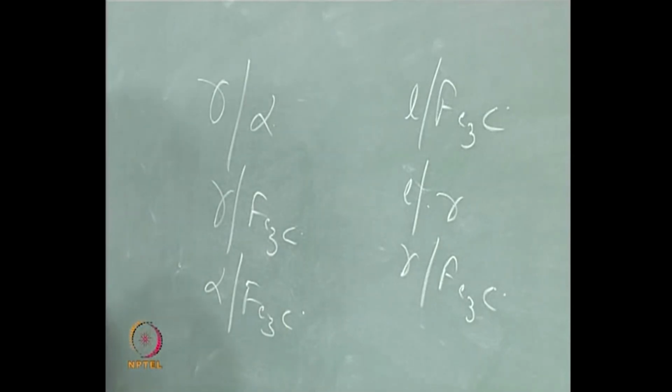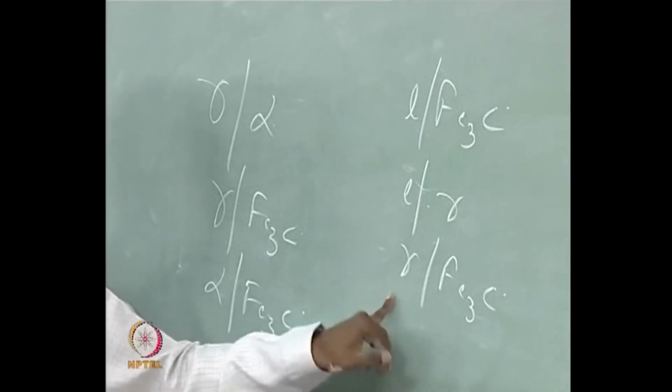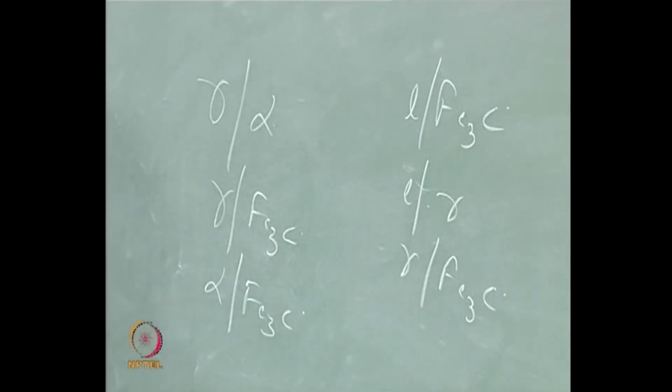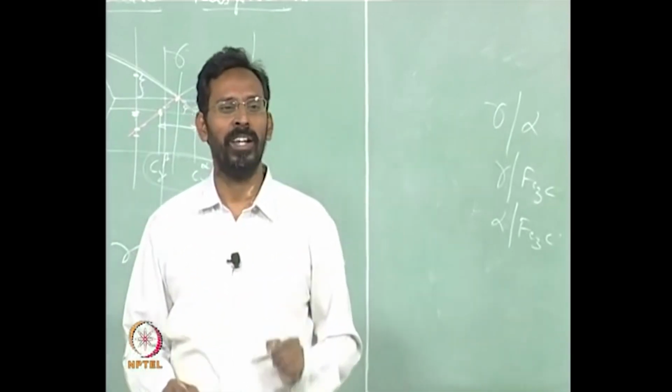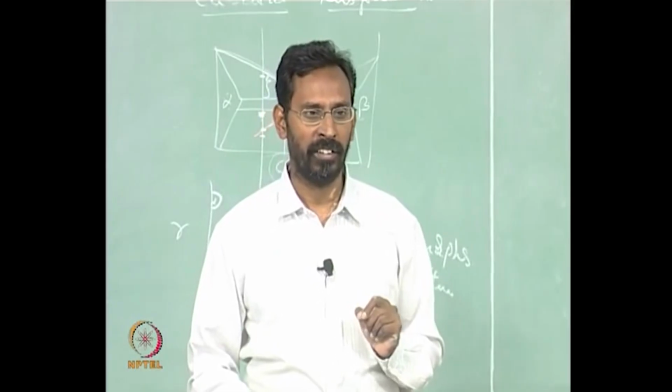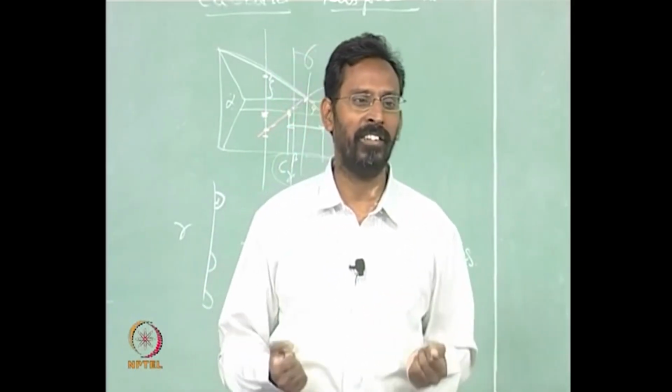When do you say interfacial energy is lower? Interfacial energy is lower when the structures are similar. For example, Ni3Al nucleating in a gamma phase, we say it forms very easily because the structures are similar. If the structures are not similar, the interfacial energies cannot be. In fact, if both the phases coming out of a eutectic are cubic, you would invariably end up with lamellar eutectics, because the interfacial energies will be similar.